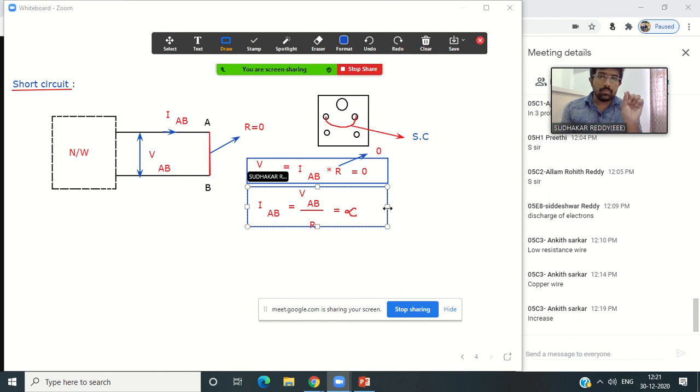Why are we using the MCB box? If the current passing through the MCB box exceeds its limits, it will simply open, and that circuit will be opened. When there occurs a short circuit, the MCB box opens the switch. Then there is no current passing through your wire. That is how we overcome the short circuit problem in our homes or in real time.